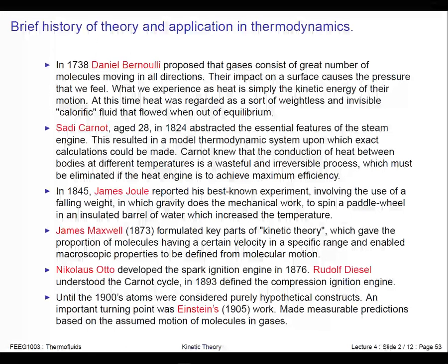And he has an engine called the Carnot engine that we're going to come across in a few lectures' time, and this is the theoretical engine that can achieve maximum efficiency. Unfortunately, you can't build it, and so practical engines like petrol and diesel engines, their efficiency is measured with respect to a similar Carnot engine. And the difference between a Carnot efficiency and a real engine is really the measure of how efficient a practical heat engine can be.